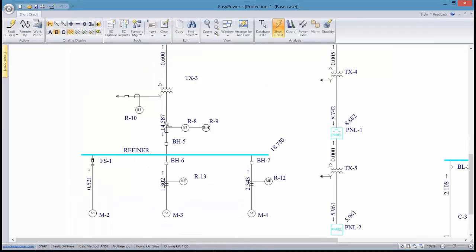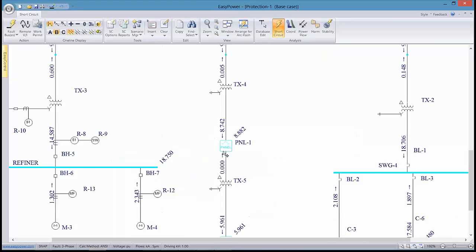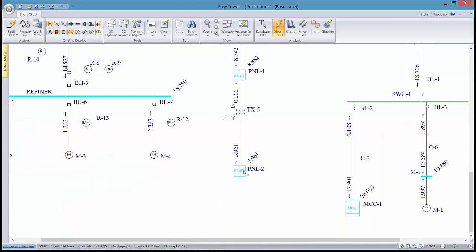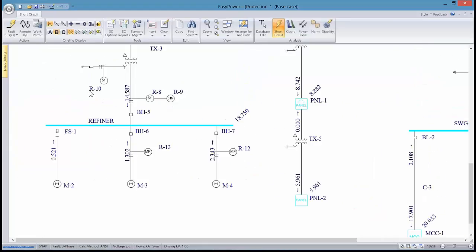bus totals. So this will be 14,000 amps down from utility, 521 amps, 1,000. All that's going to add up at a vector sum for the bus loading. And likewise on this panel, we'll see 8,742 coming down, nothing coming back from the load because apparently we have nothing down here on the load. Okay, so that's current, half cycle fault current.